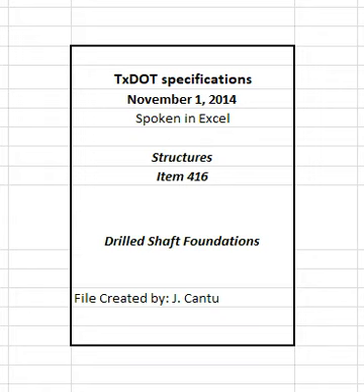Remove loose material and accumulated seep water from the bottom of the excavation before placing concrete. Place concrete using underwater placement methods if water cannot be removed. Place concrete as soon as possible after all excavation is complete and reinforcing steel is placed.